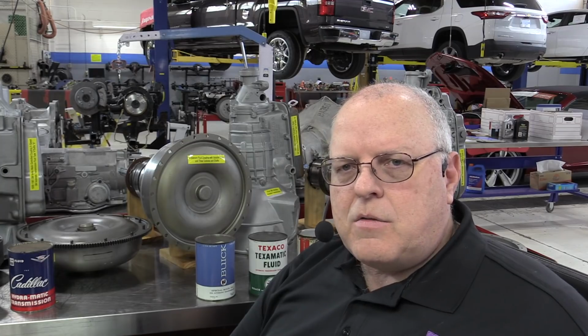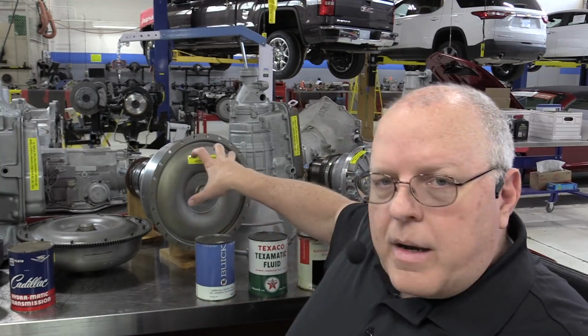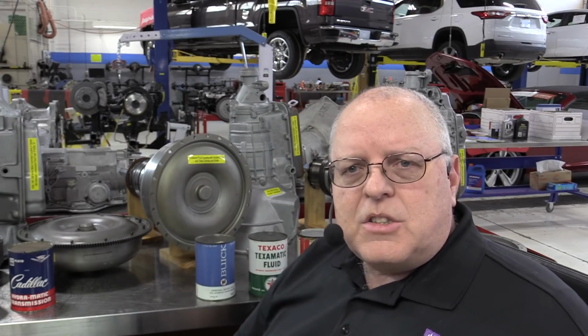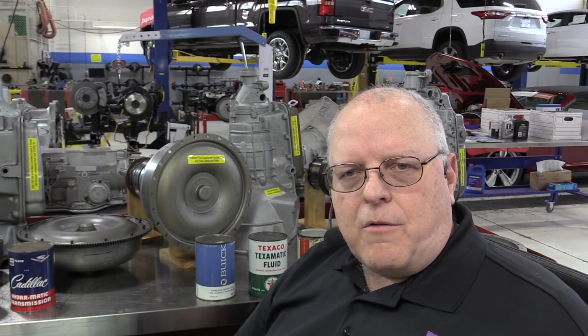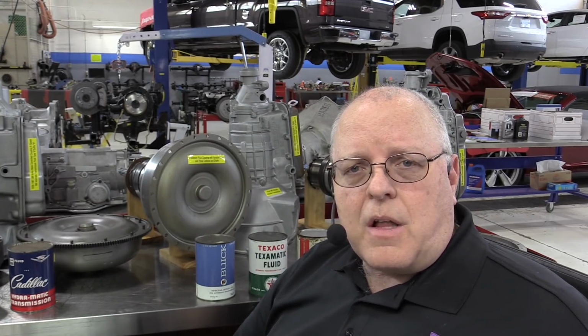But this transmission, as the engine speeds up and the vehicle speed increases, it changes which turbine is most effective, and it has a variable pitch stator inside of it. The angle of the vanes on the stator can be varied in 2 positions on this one. There's another model that's variable in more than 2 positions. If you've ever driven a vehicle with a continuously variable transmission, this transmission, I understand, would drive just like that.